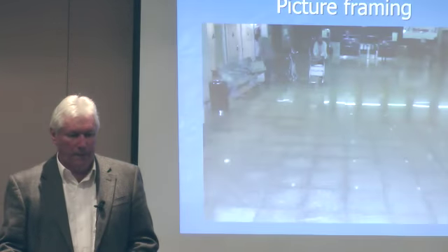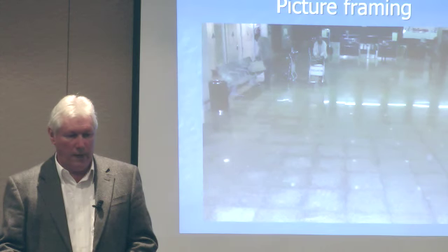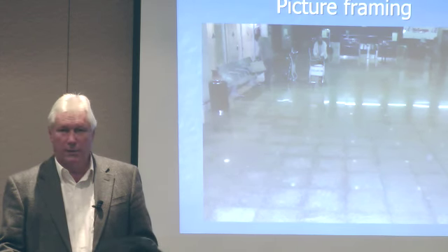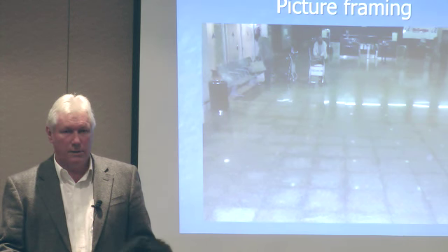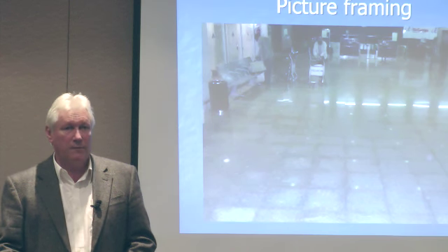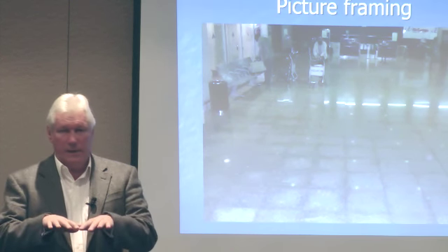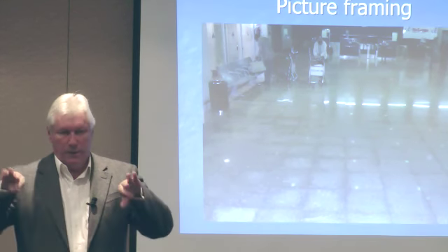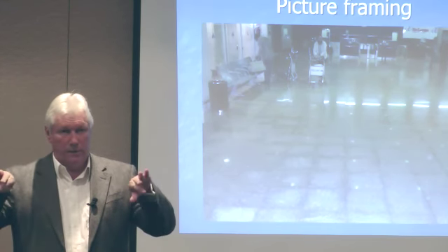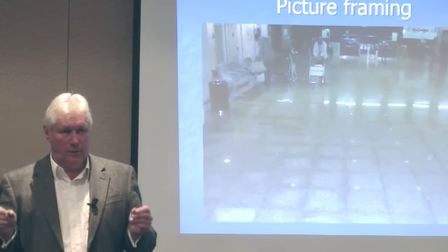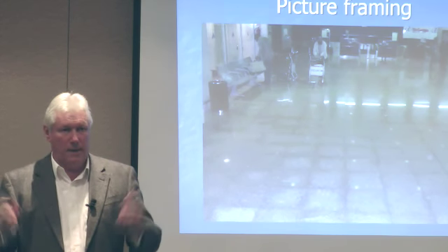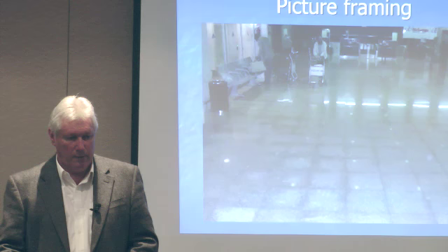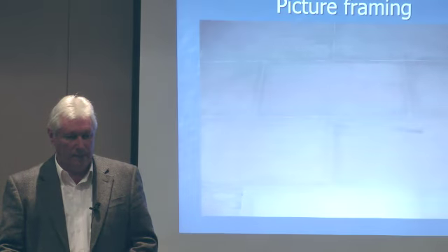We can get this granite in an airport overseas that I saw, where there's obviously a leak somewhere, but the moisture travels up through that, wants to achieve equilibrium. So it comes up through the joints first. The stone's relatively dense, and it can't come really up through the stone, or it takes a long time. But it's much easier for the water to move out and up through the joints. The joints are relatively porous, so most of the water keeps on coming up and rising up through there and giving us the picture framing effect.